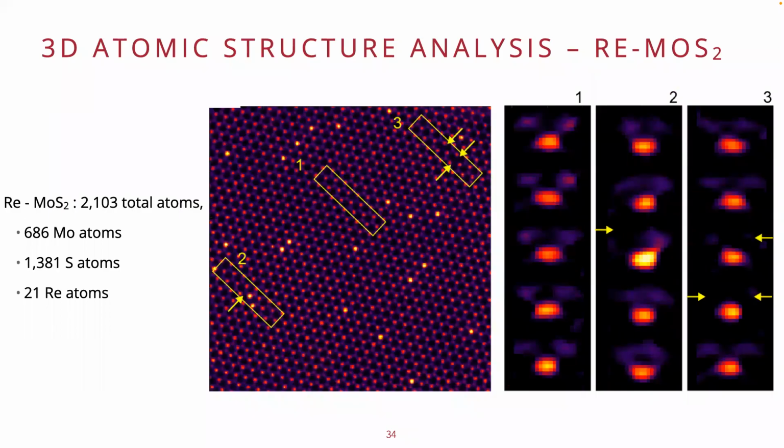So originally, or at least I personally believe nowadays, it's quite easy to see if you have vacancies because you have such a decrease in intensity in your TEM micrograph, so that we can at least pinpoint that in this column or in this tube.